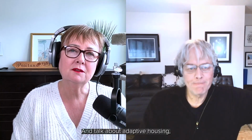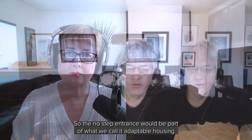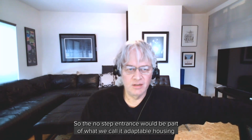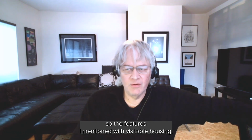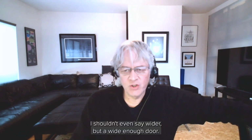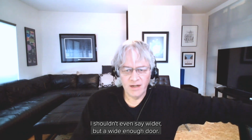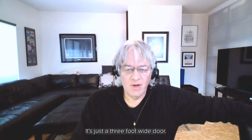Right. Now, talk about adaptable housing, what that is, and that speaks to the no step entrance. Yeah, so the no step entrance would be part of what we call adaptable housing. So adaptable housing is really one step up from visitable housing. So the features I mentioned with visitable housing, that being the no step entrance, the wider door and hallways. I shouldn't even say wider, but a wide enough door. So we're not asking for anything special. It's just a 3 foot wide door.